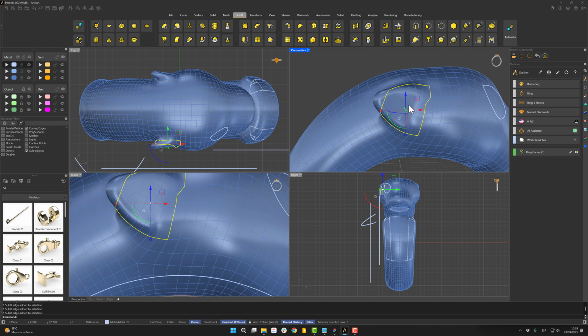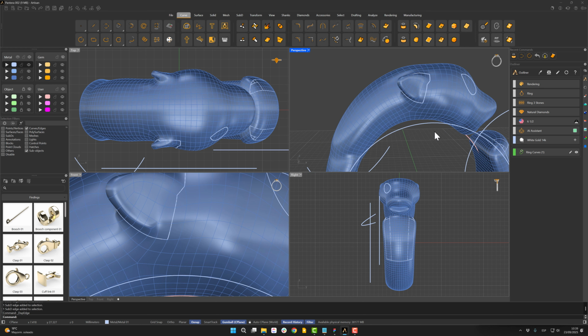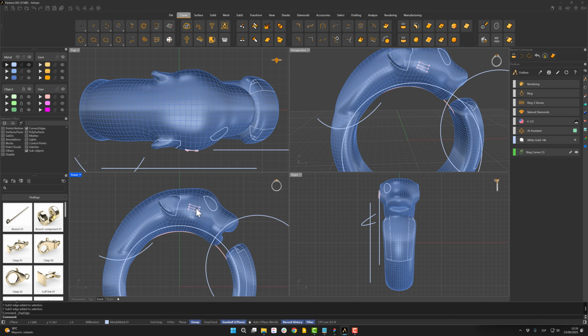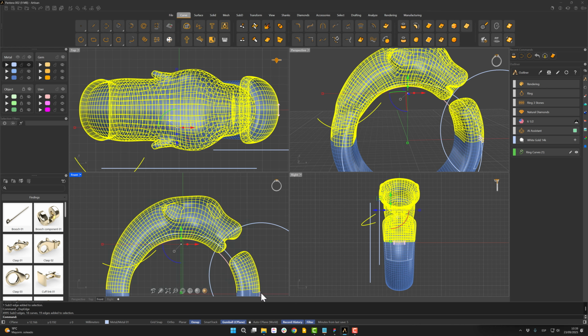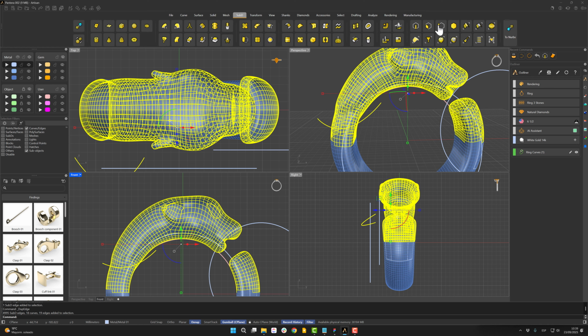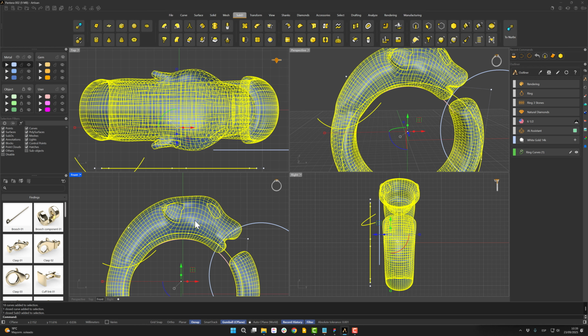Once you have all the edges selected, go to the Curve tab and use the Duplicate Edge command. Now deactivate the filters and select both the model and the reference curves. Press the Trim command and cut the areas where we will not position gems.